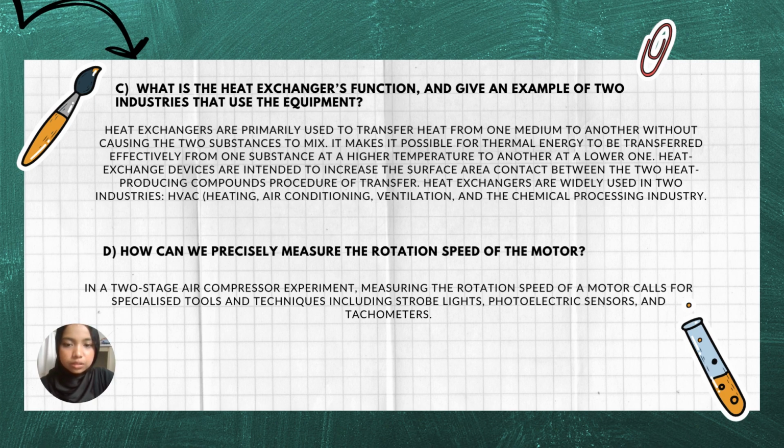For the last question, how can we precisely measure the rotation speed of the motor? In a two-stage air compressor experiment, measuring the rotation speed of a motor calls for specialized tools and techniques, including strobe lights, photoelectric sensors, and tachometers.